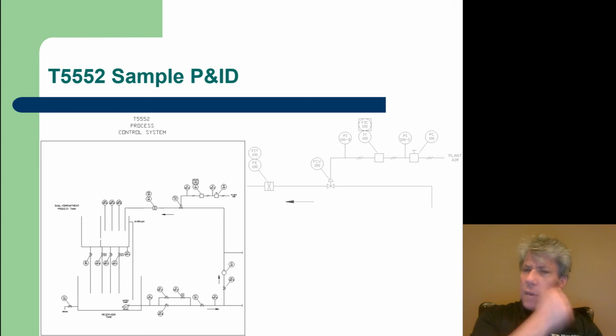Now, why they used IY here, I'm not sure. I'm beginning to forget some of the details of these various systems, but I do know FIC 100 would be a flow indicating controller, and that thing's job is to control the flow rate going through the piping that FCV is connected to, the flow control valve, FCV 100. Now notice these 100s all go together.